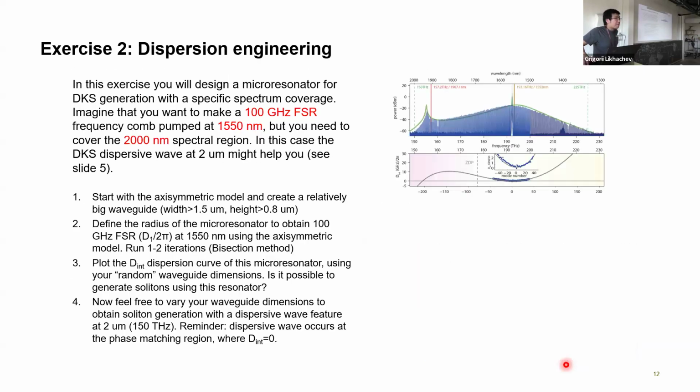Also, a bit more advanced, is how you actually design your waveguide for a microresonator to get the dispersion profile that you actually want, to get a dispersion wave at specific wavelengths when you are generating the soliton.